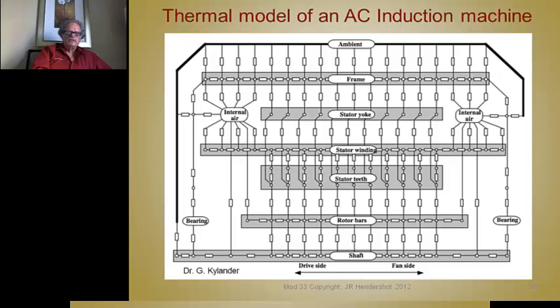For example, you've got a stator and you've got slot liners in it. Well, are the slot liners touching all the conductors? Are the slot liners touching the slot all the way around? No, never, and it varies from one machine to the other. So the ultimate temperature of the machine will be right, but the time scale of these different components of the machine won't be right. So you still have to take measurements of this.